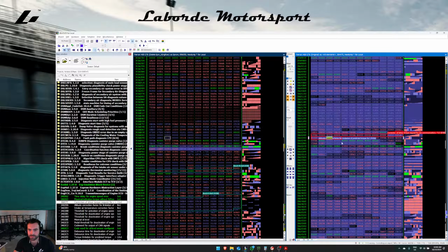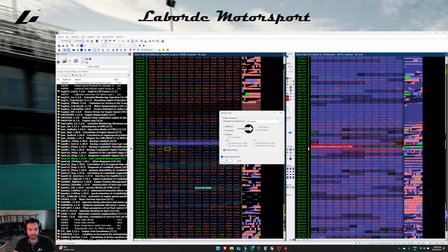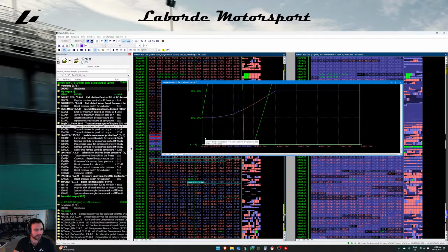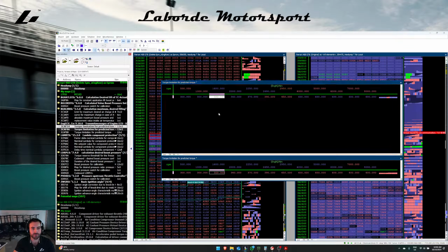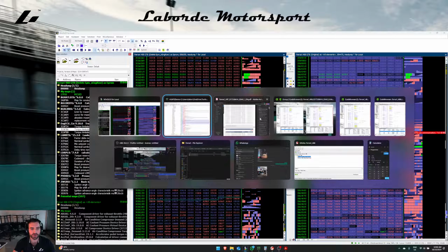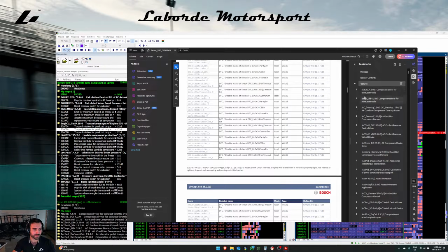So there are some maps here, which is exactly what we're after, right? There's three of the torque limitation for predicted torque, and these are only used in one module that I can see, and that's the module used for the transmission of messages. So what we're going to do is look for the relationship of this map to the measurement variables or the RAM variables. Then we're going to try and find it that way, because I know that this map exists in both software versions. Therefore, the RAM variables should exist in both software versions,